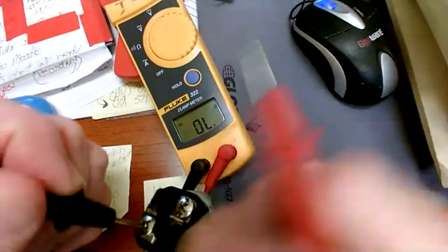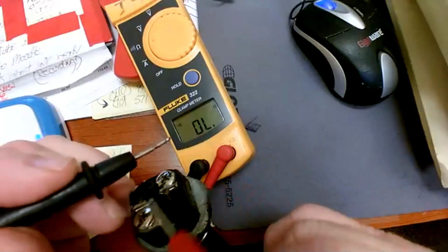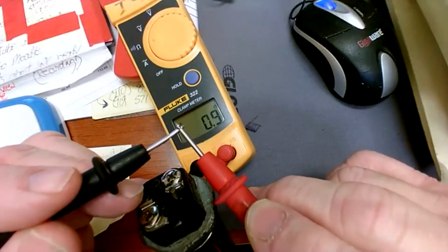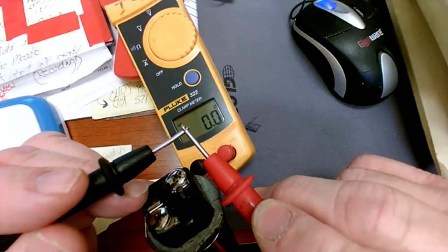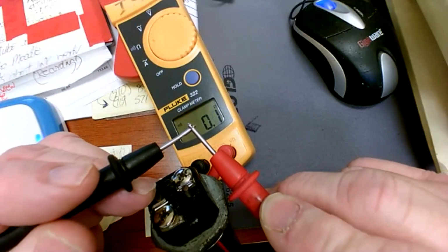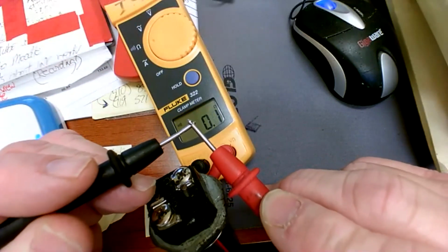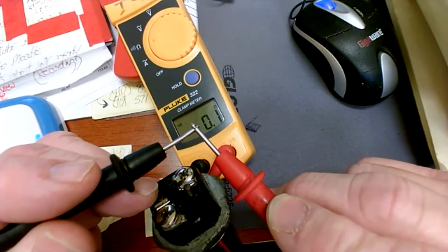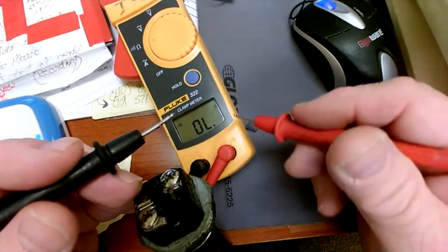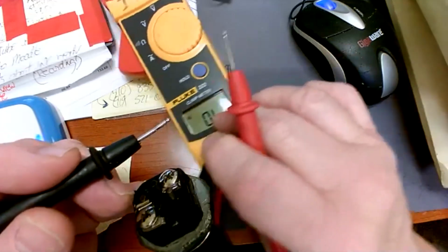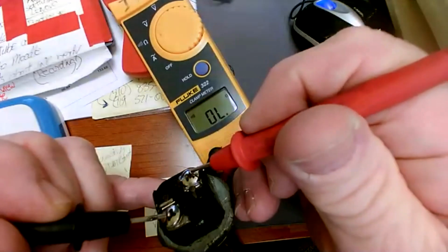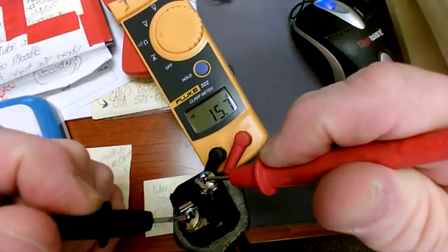So I'm coming directly, and also look, before you check the resistance of it, put the test leads together. And you see it says 0.1, and that's great right there. It's got way less than 1 ohm of test lead resistance. See that? So 0.1 is actually the resistance of my test leads, okay? You can subtract that from this reading and get an exact reading of the heater element. So let's go now to the screws on the element. And what are we reading?